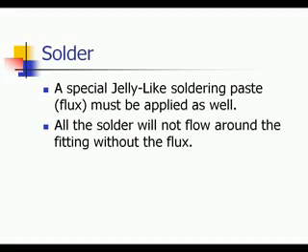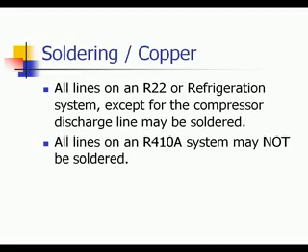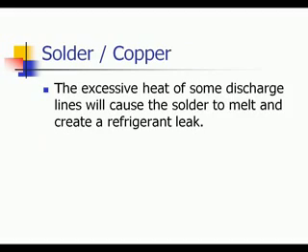You've got to get off whatever dirt, chemicals and oil the factory puts on them before they're shipped, or the solder will not flow. A special jelly-like soldering paste called flux must be applied as well. The solder will not flow around the fitting without the flux. It actually provides some of the capillary action to pull it in.